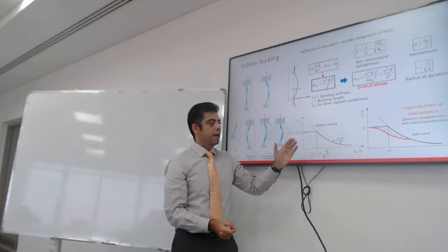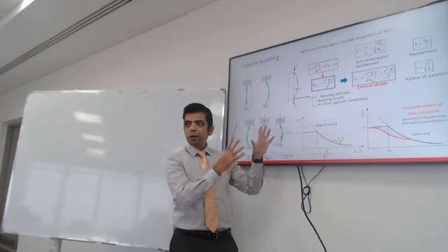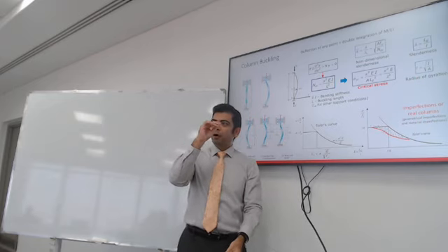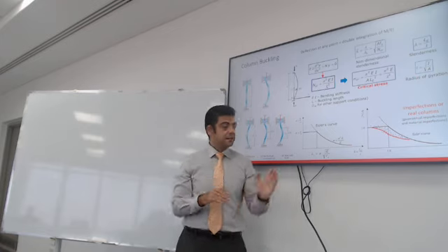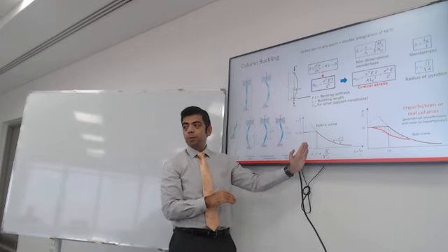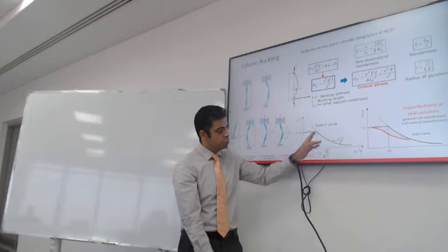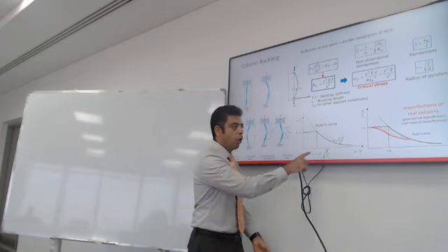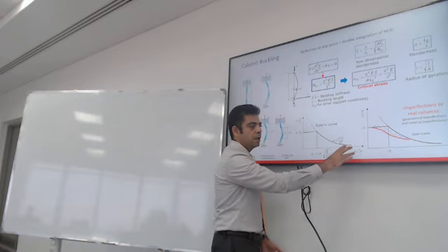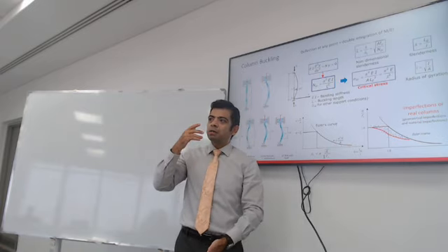So it's like a telltale curve of whether your column is going to buckle or going to fail under compression. The shorter it is, the more likely it is to fail under compression. The longer it is, you significantly reduce the axial capacity, all the way to, theoretically, the column just can't take its own weight.